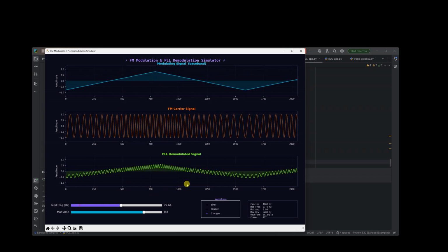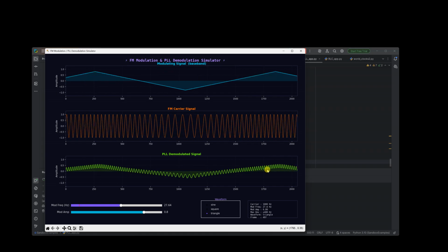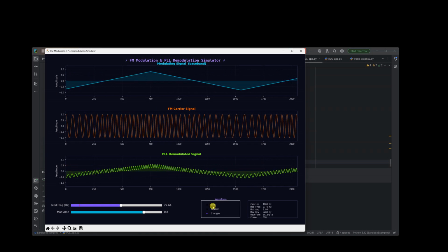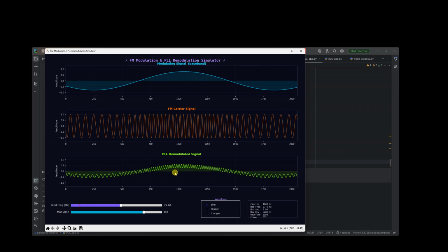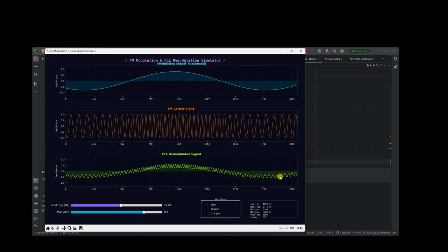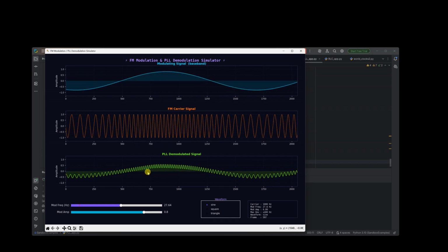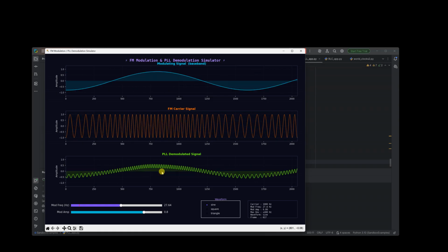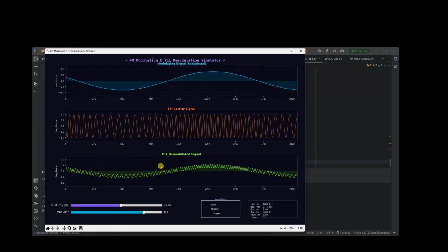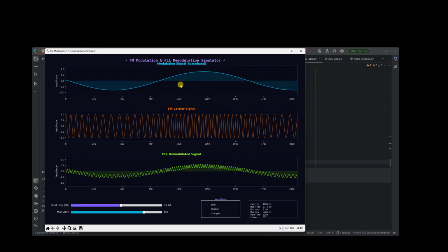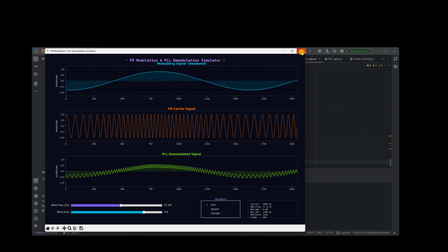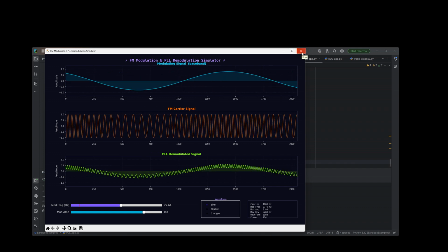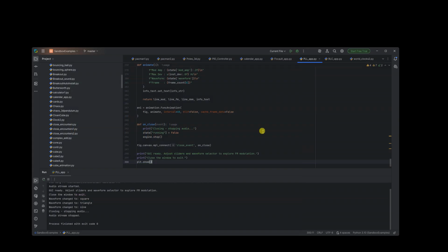I'm going to stop this because of the noise. How do I turn it off? One thing I didn't put in was the noise to turn off. But what you're seeing here is a 2F carrier feedthrough of the phase lock loop. Okay, that's standard. You could filter that out, but it's twice the carrier frequency in a phase lock loop. This is how your FM radio works. I never thought I'd see one running on a PC like this. So that's a phase lock loop demodulating FM.